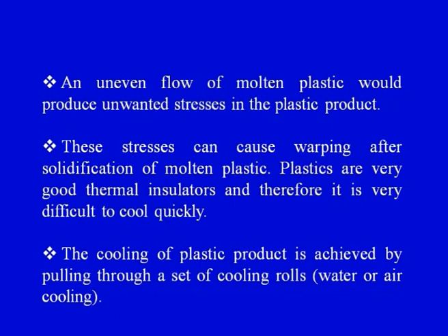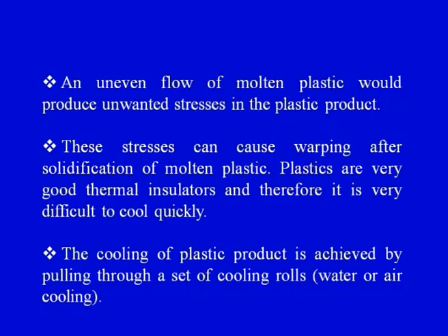These stresses can cause warping after the solidification of molten plastic. Some of the effects are given: if these stresses are present, and they are present because of the uneven flow of the molten material in the plastic product, they can cause warping after solidification. Plastics are very good thermal insulators, and therefore it is very difficult to cool quickly. So that is another issue that is involved.